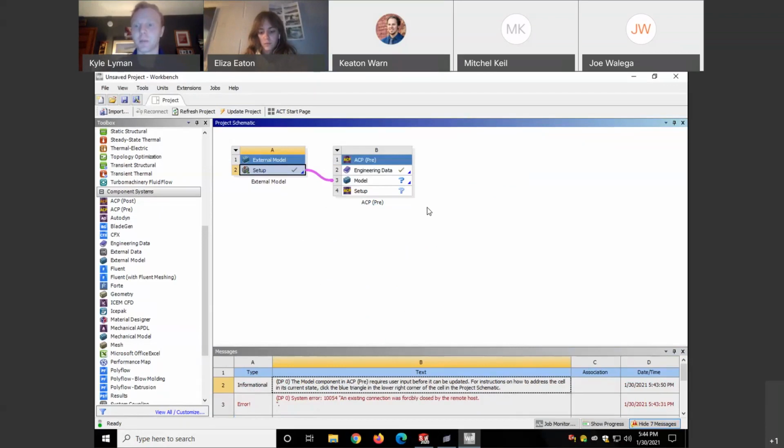It is, yeah. And I noticed also that you had Shell 63 for quads, and you also had Shell 63 being used for triangular elements. I did, yeah. Well, that's fine, but what you need to know is that's a degenerate quad. And at that place where it goes to the triangular tip, it's going to be artificially stiff at that point.